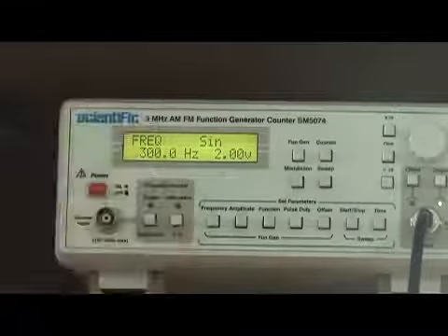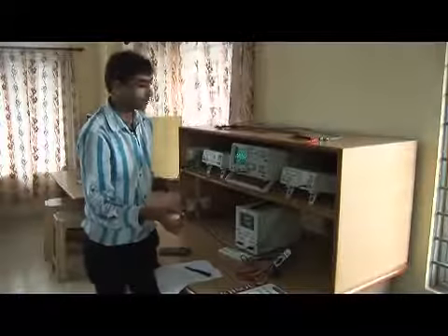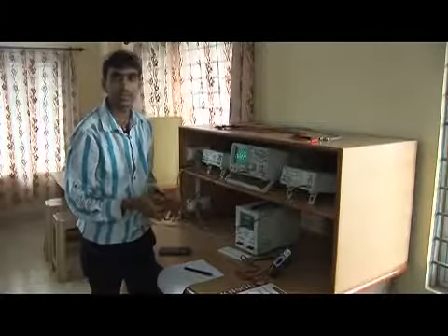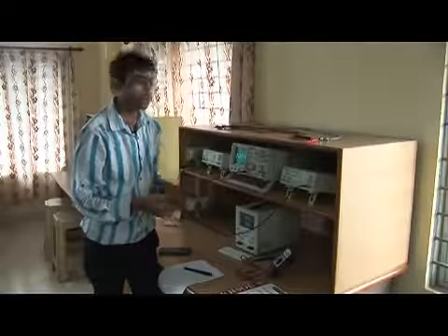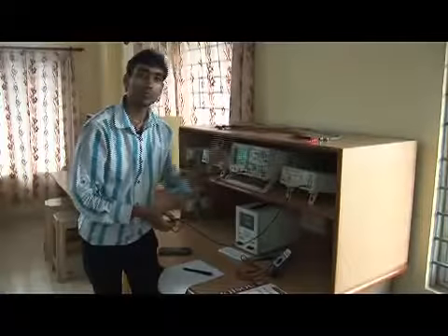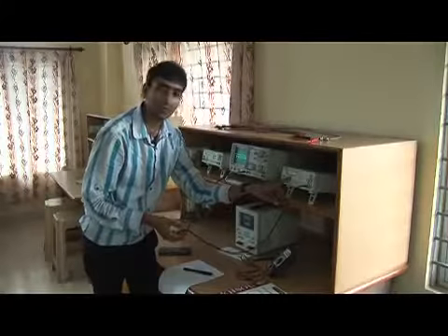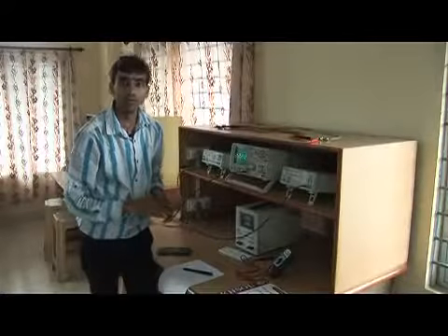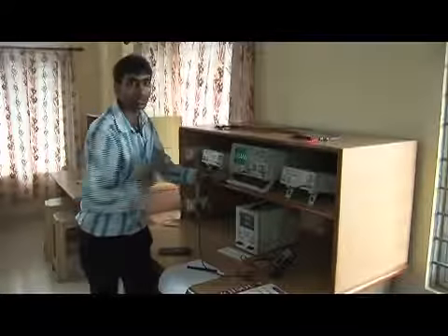Again I am saying why the difference is there, because of this wire being used. I am saying again and again that every wire you are using in an electronic circuit or in electronic apparatus has some resistance. Due to that resistance, the resistance may be offered to the frequency, the voltage, or the current. Due to that, if it is 2 volt, we were getting less than 2 volt, that was 1.9, and as it is 300 Hertz in the frequency, we are getting less than 300 Hertz, but it is approximately the same. So this is how we calculate the amplitude and the frequency using a CRO.